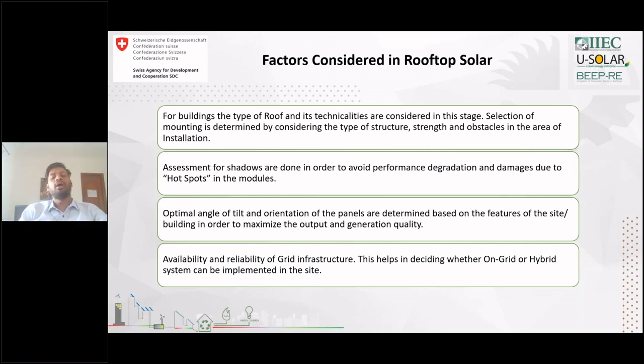And how do you go ahead with freezing the tilt angle? If you have observed any solar system, it will not be placed at 90 degrees or zero tilt angle. It will have some amount of tilt. How do you determine this tilt angle? The general rule is to identify the latitude of the place of installation.